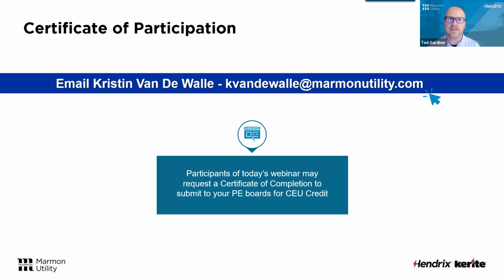The reason we have that temperature rating is we don't want to cause any damage to that covering. So those numbers will be good, and that's what we use for our ampacity ratings. Like I said before, we make it in black and gray, and that also affects the ampacity as well.